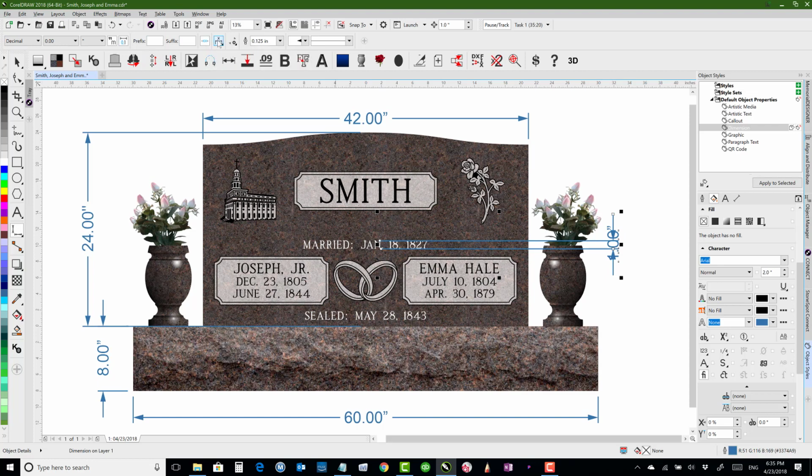So we'd come up to this, and under text position we want to do force text horizontal, and we might even change the style of the line here from that style to maybe just right click and get rid of it altogether, so that it doesn't even have a line. That way it doesn't get too complicated.